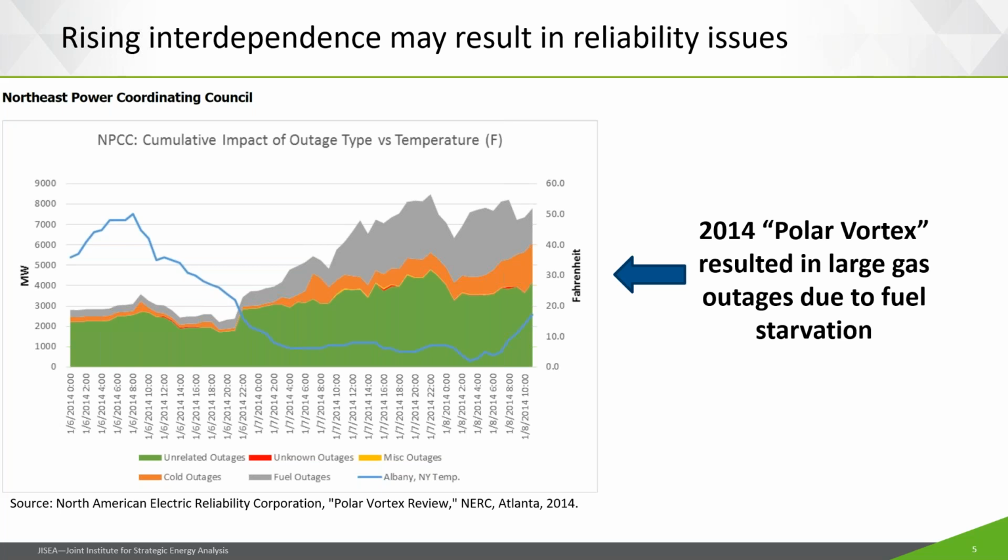So one key thing we have to keep in mind here in the United States is that the contracts for most of the residential and commercial natural gas customers are guaranteed contracts. So you have to be able to deliver that gas to them. Whereas on the power system side, those contracts allow for interrupting the service if there is a shortage of natural gas. And so this key difference in contracting between the two types of customers, the so-called city gate customers versus the generation customers, leads to different impacts on the power system as well.